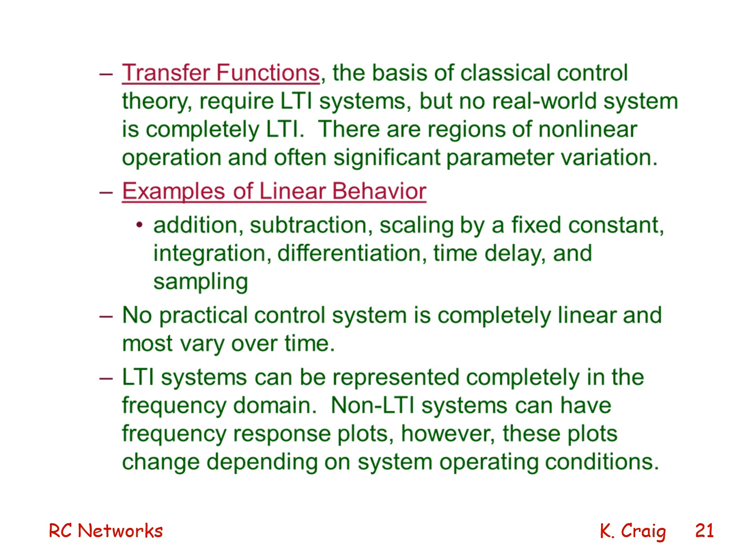Examples of linear behavior are addition, subtraction, scaling by a fixed constant, integration, differentiation, time delay, and sampling. No practical control system is completely linear, and most vary over time. LTI systems can be represented completely in the frequency domain. Non-LTI systems can have frequency response plots. However, these plots change depending on system operating conditions.